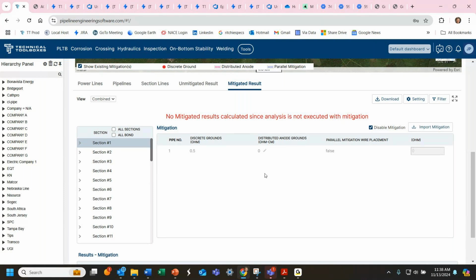They've already had leaks from that low soil resistivity. It doesn't take much voltage, a couple volts, and you're in trouble of AC. Even across here in the Brazos River, just east of Houston, 30 ohm centimeter brackish water, they had a leak with a half a volt of AC.